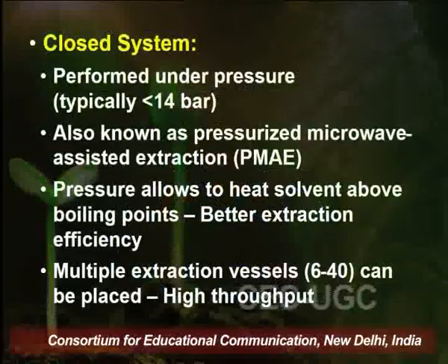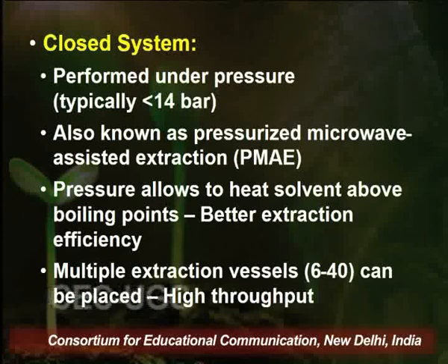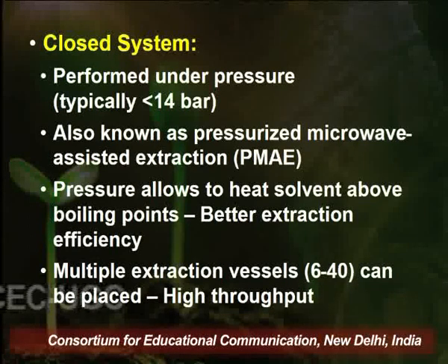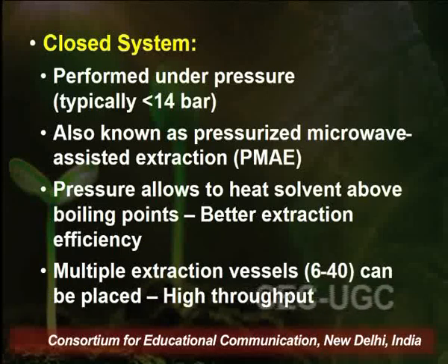Closed system vessels, as I told you, are performed under pressure, which is typically less than 14 bar, and since they are performed under pressure, these are also known as pressurized microwave assisted extraction. The major advantage of this system is that whenever you apply pressure, you are allowing yourself to heat the solvent above its boiling point, and therefore it improves the overall extraction efficiency. But this kind of system is not meant for thermosensitive or thermolabile constituents.